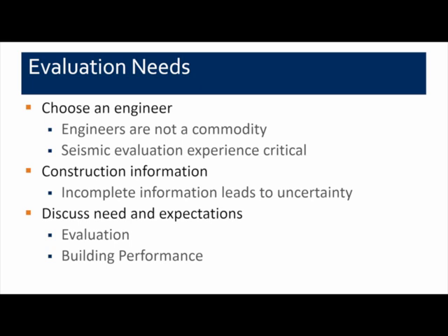So when you're evaluating the building, some of the important considerations are, one, to choose an engineer to do this evaluation, recognizing that engineers are not necessarily a commodity, that seismic experience is very critical to getting a good and proper evaluation for the building. Having good information on the construction of the building is critical to getting a good evaluation.